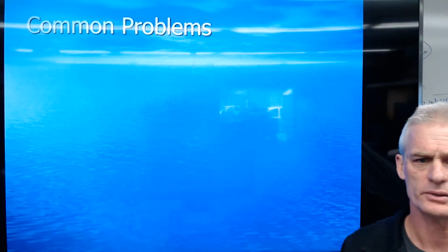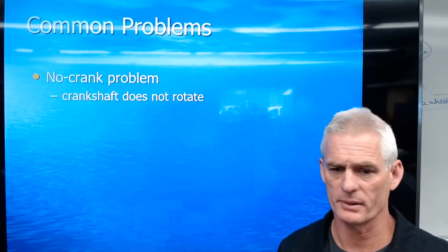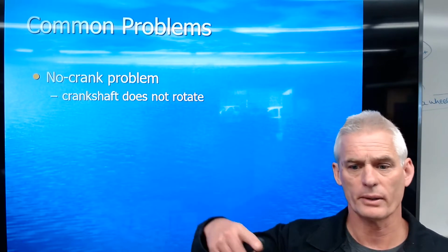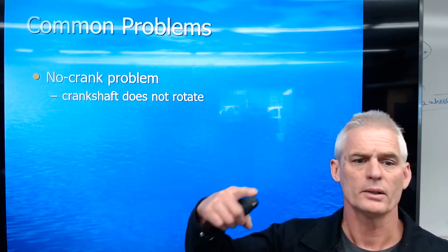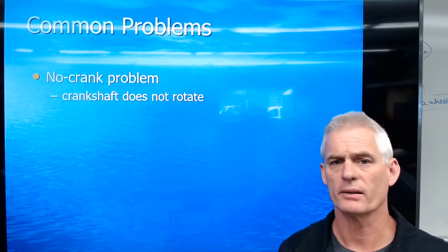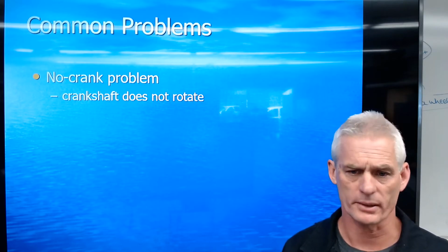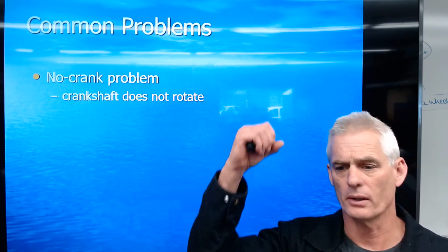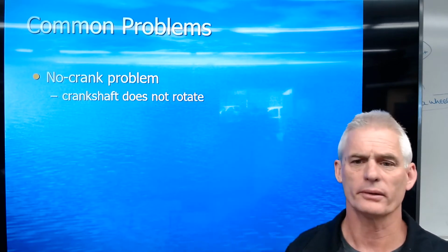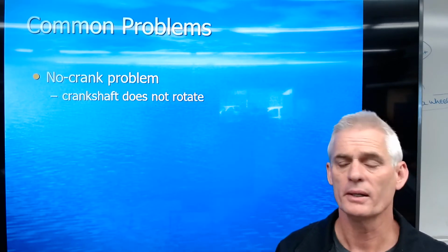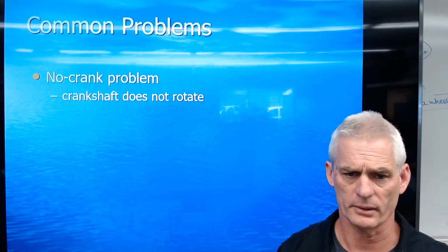So the first thing is common problems would be a no crank problem. No crank meaning the crankshaft is not spinning, so we are not initiating that intake, compression, power, exhaust four-stroke cycle. So you don't hear the crank going. You turn the key on, you go to the crank position, maybe you hear a click, maybe you hear nothing, okay?